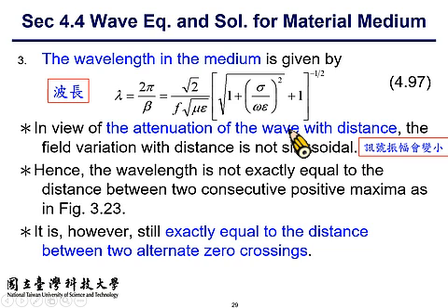conventionally, we are looking at the position, say the maximum. Conventionally, we usually check the maximum position. If they reach the same amplitude, then we can say this is one wavelength. However, considering the presence of attenuation, the signal will become smaller and smaller as it travels. So the definition should be modified, because the peak, the maximum value, will become smaller and smaller as it propagates. So the definition for wavelength should be changed to checking the zero crossing interval, which will be more convenient to define the wavelength.